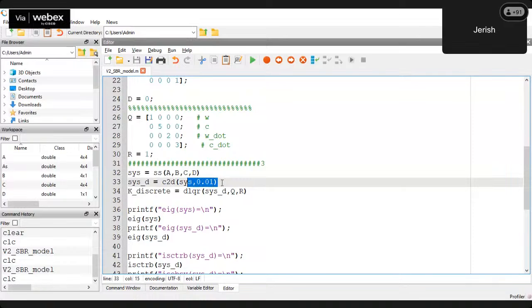So now this is the step we'll need for deploying our system on a microcontroller or any processor. Since that runs on discrete clock cycles and discrete execution time for every control calculation, we choose a sampling time of 0.01 second over here. We feed it into the C2D function of Octave, and this gives us a discretized system by applying Z transform to the time domain system,